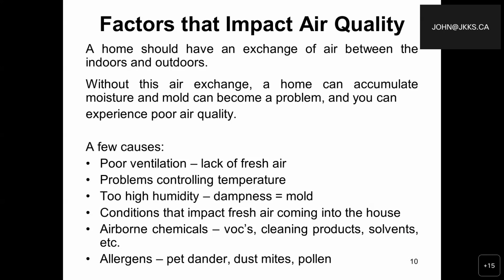Okay, so on the lower portion of the slide, we will see a list of factors that impact the air quality. Without air exchange, a home can accumulate moisture and mold, as I've been talking about, and become a problem, and you can experience simply poor air quality. A few of the causes could be poor ventilation, so lack of fresh air coming into the house, problems controlling the temperature, too high a humidity, thus potentially dampness or development of mold, conditions that impact fresh air incoming the house.